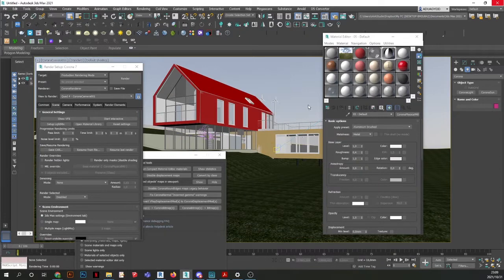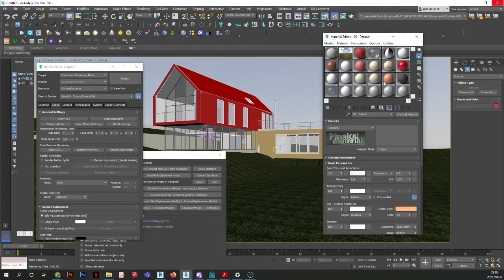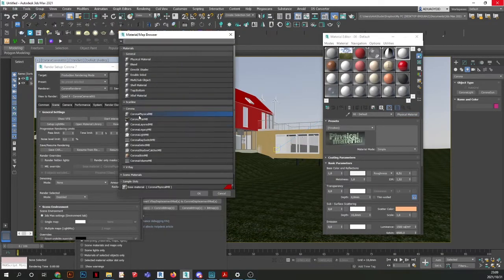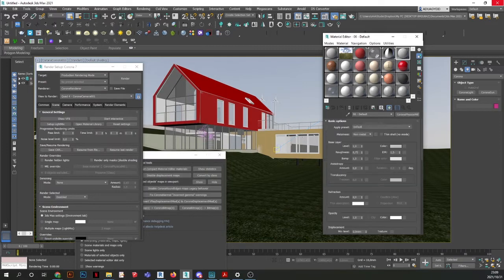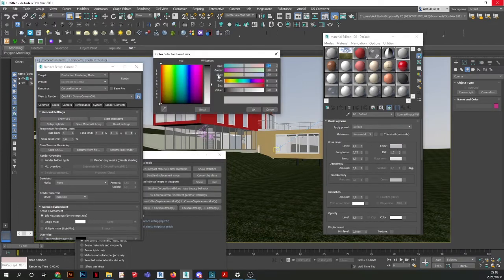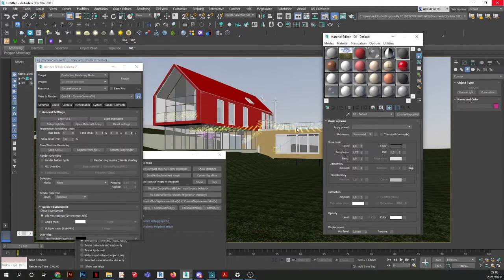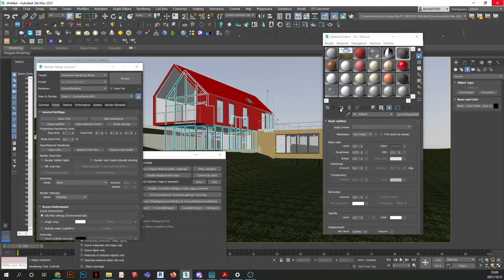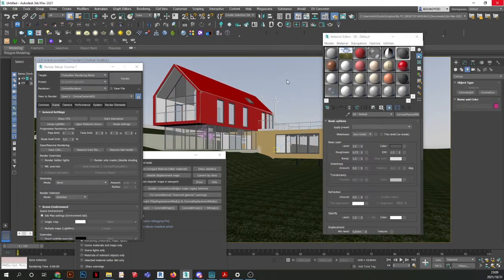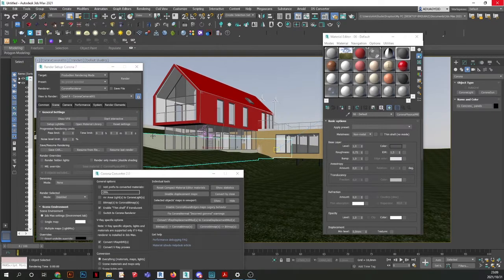Okay, I'm going to create my own gray material for the frames. Also, when you're not too close to an object, you want to reduce the reflectivity and all those things, because it really consumes the rendering time.